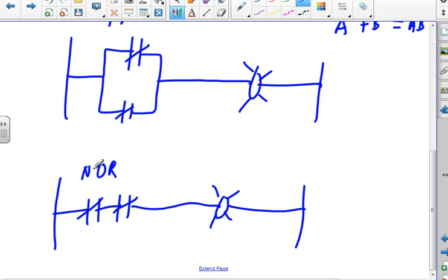I put labels on the wires as I was doing it. Now, if I had more money, I would invest in wire numbering kits, and when you did your wiring, I'd make you wire number everything. Wouldn't that be boring? But if you look at any real piece of gear, every single wire has a wire label at both ends.